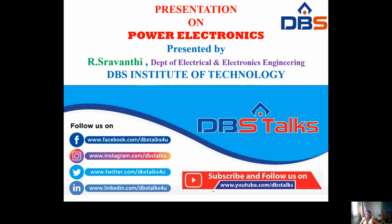So three phase full control rectifier is also known as full controlled bridge control rectifier. And here we are using 6 thyristors connected in the form of full wave bridge configuration. All 6 thyristors are controlled switches which are turned on at the appropriate times by applying a suitable gate trigger signal. The three-phase full converter is extensively used in industrial power applications up to about 120 kilowatts output power levels, where two quadrant operation is required.